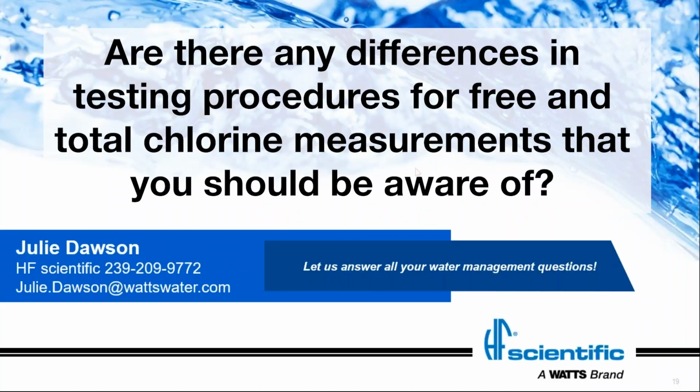In DPD, the differences in testing procedures are there's a different reagent used for free chlorine and total chlorine, and for free chlorine, we want to measure within a certain time frame. I think the reaction time period is 30 seconds, and then we want to measure it within the 30 seconds to a minute after that. For total chlorine, I think the reaction time is 3 minutes.